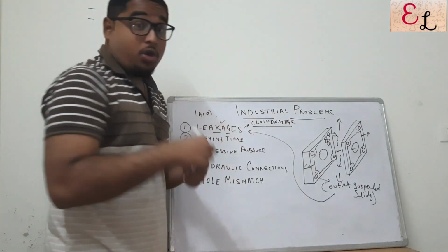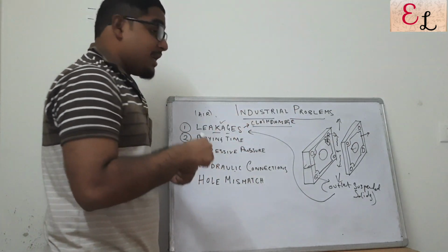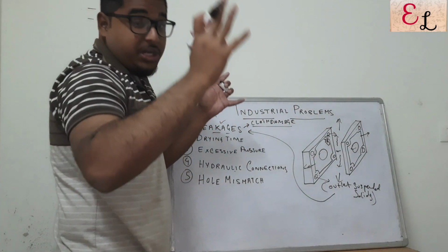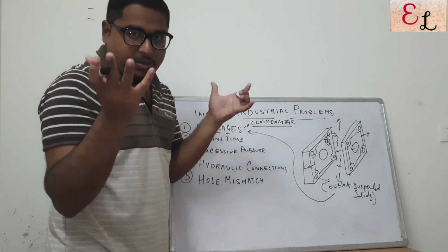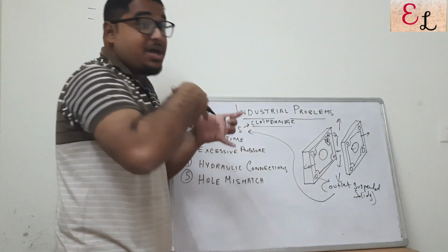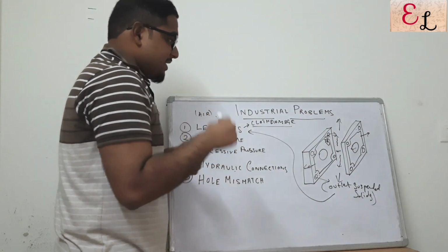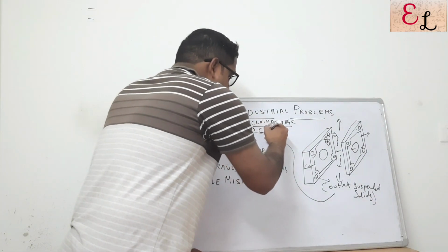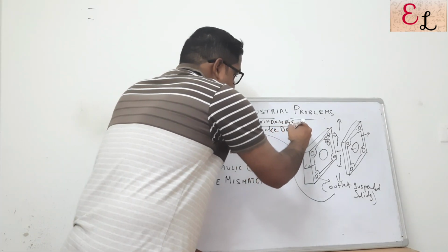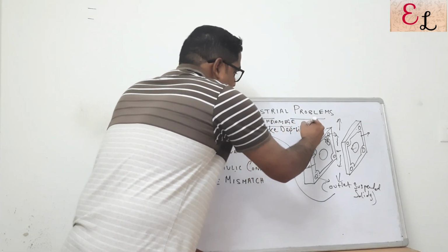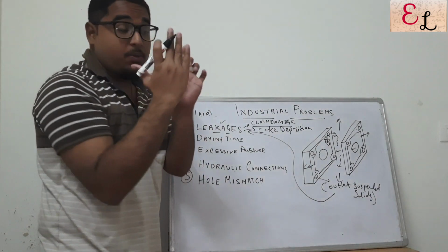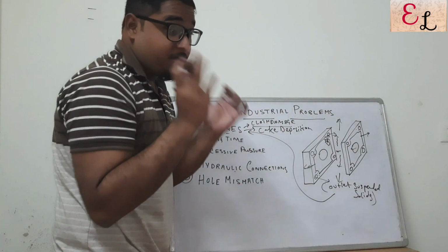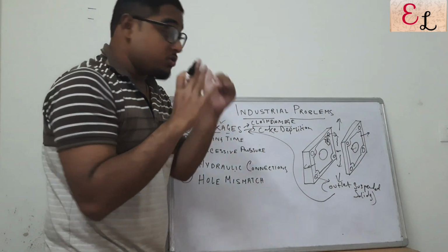So in this case, the cloth is not porous, but you will have to understand that the visible leakage we see through the splashing of the water or the filtration medium from the top or the side of the plates is primarily due to heavy cake deposition on the cloths. If the cake deposition is high on the cloths, there will be excessive pressure in the system and it will not allow further filtration medium to pass through because of the high resistance path.